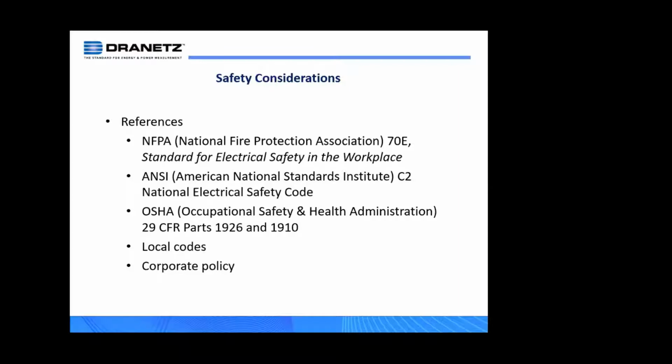I have actually seen people reach in with their bare hands in 480 gear and things of that nature. So you want to make sure that when you're going out and connecting an instrument, you adhere to these standards. There's no such thing as a shortcut. Shortcuts will get you into trouble.